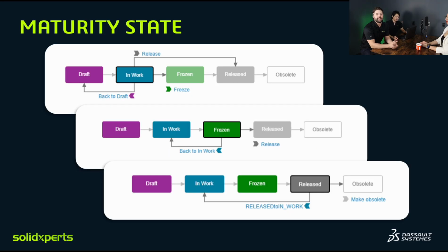You can also track and set rights using maturity states and life cycles. The 5 states shown here on the engineering definition maturity graph, quite the mouthful, are going to meet the needs of the mass majority of clients and are not meant to be customized. That's where change actions, issues, and routes can be used to tailor a design release process and take care of all those more complex situations.